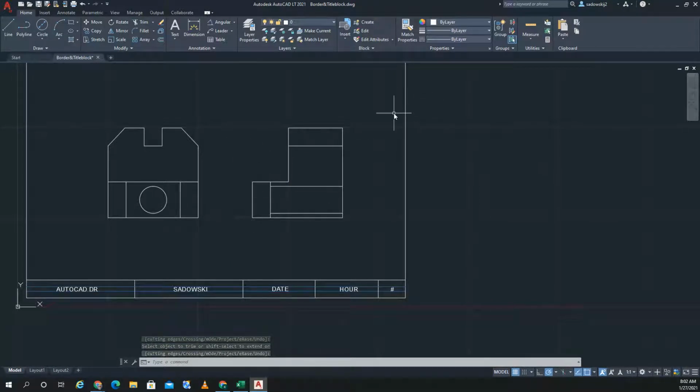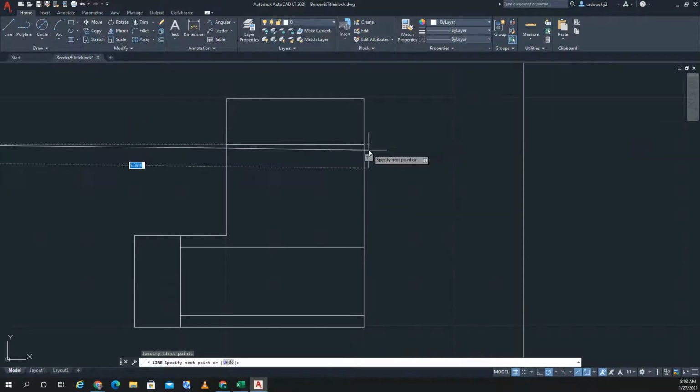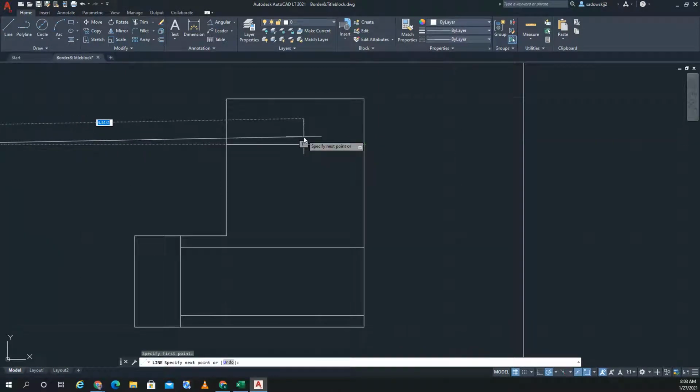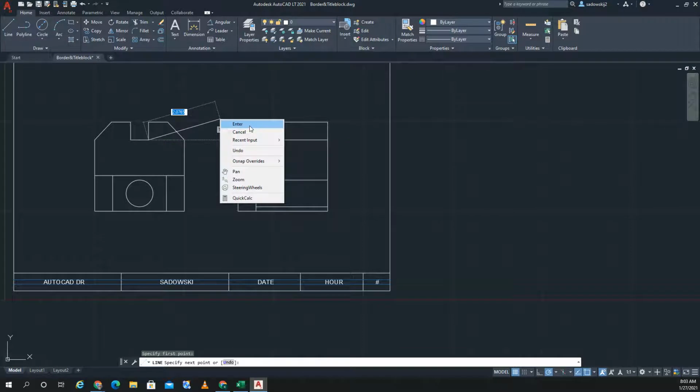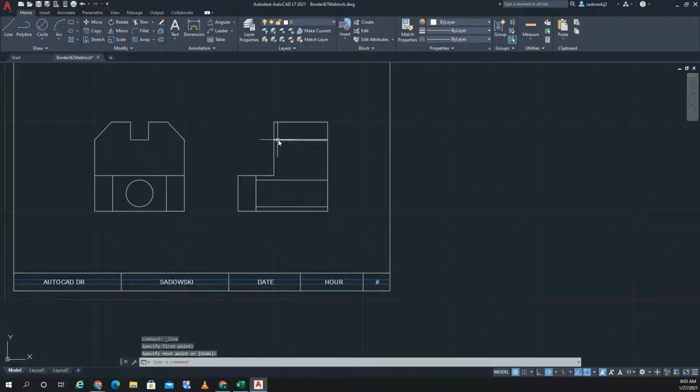But these are hidden. But I'm going to wait until I do this last one over here, which lines up with this object line. So what do we do when we have a hidden line that lines up perfectly with an object line? You just leave it. In the order of precedence, an edge or an object line where there's physically something there on the view we're looking at takes precedence. So you won't even see the hidden line because it's covered up by this one. So now we can go here and change all these up.